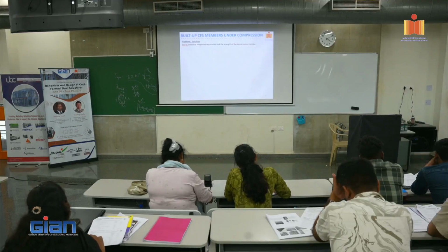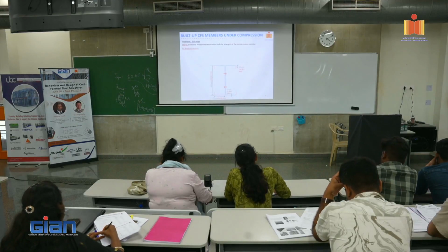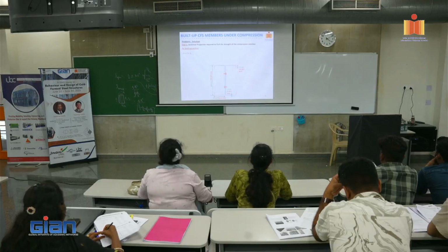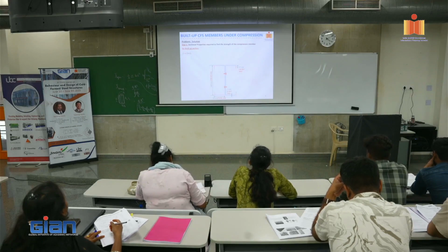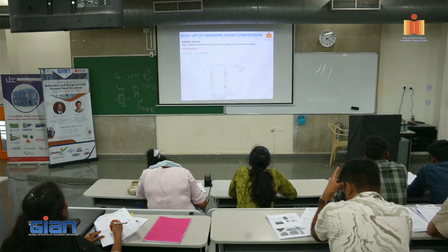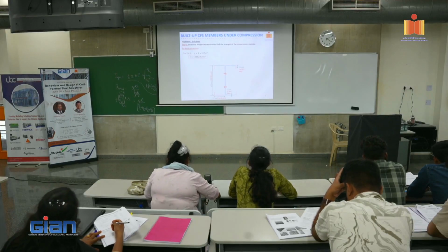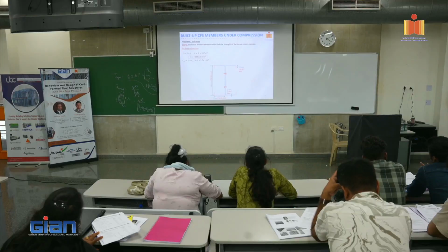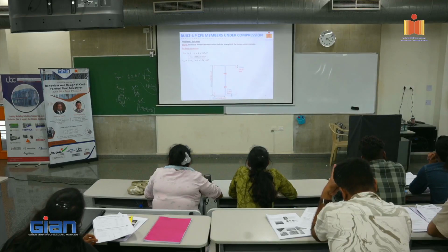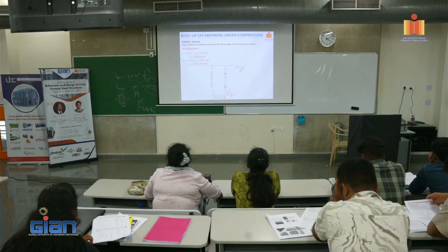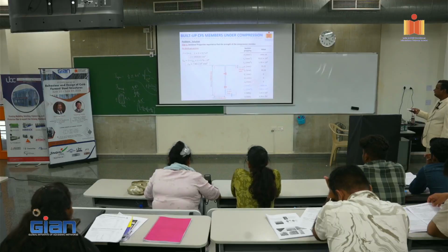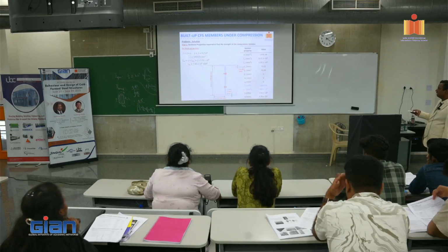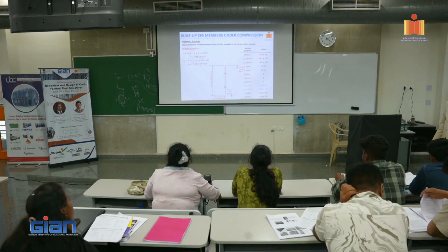Now, after having done that, for built up sections, you have J equal to 2 into Ji. Ji is the individual, right? So you can add that one. So 2 into 917.27, J becomes 1834.54, right? Cw, warping constant, is also 2 into Cwi, you get this value, 7.48 into 10 power 9. So you have increased this one, J is added, Cw is added, right? The new values. Any questions on this so far?